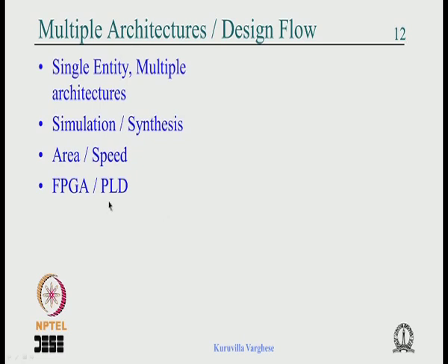So you see the VHDL idea of providing multiple architectures is a really good feature it has, and you should be able to use it. But in any case, when you have multiple architectures, whether you simulate or synthesize, at the beginning you have to choose which particular architecture you are going to use. That has to be specified, and that syntax is called configuration. As we proceed a little ahead we will see the configuration syntax.